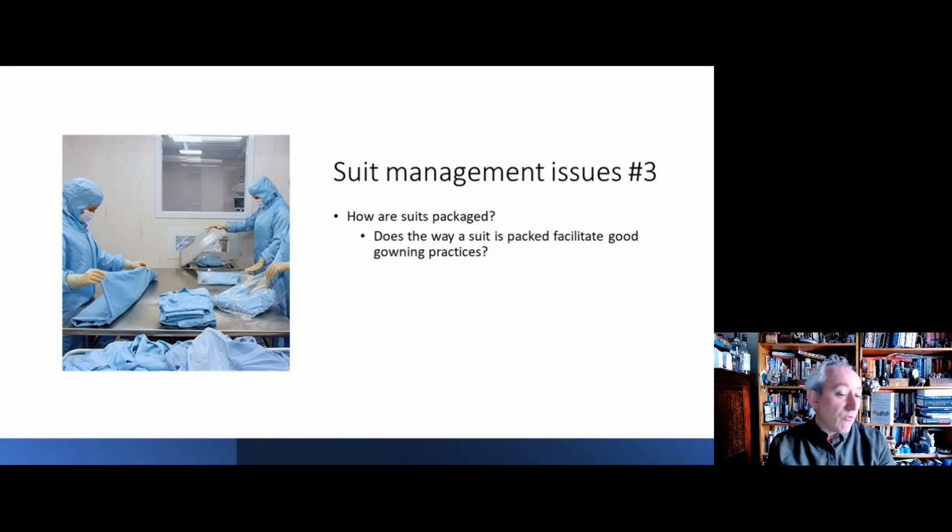So clean room floors generally will have the higher levels of contamination, which is why there's a lot put into the way gowns are packaged, and there's a lot put into practicing gowning. A new starter coming to BPL will probably practice, or should be practicing gowning, dozens and dozens of times before they go into a clean room for the first time, which is why the whole training centre has been constructed to allow that practicing to take place.